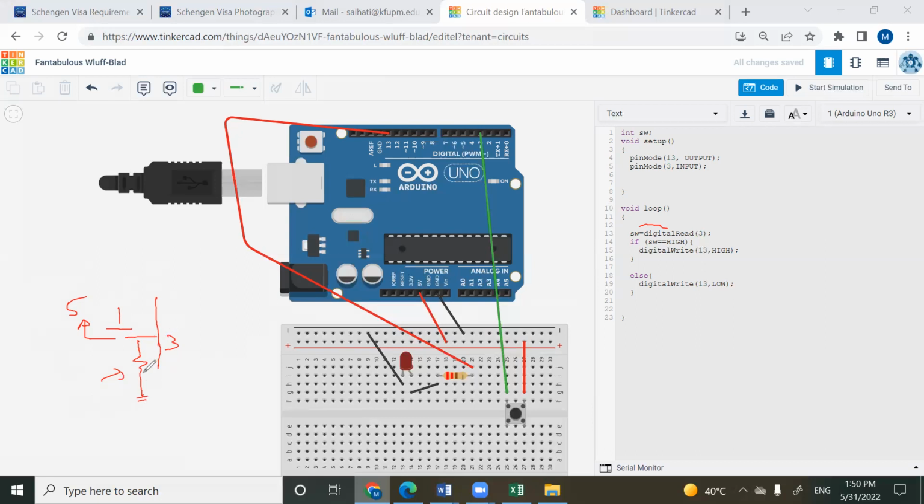So actually this is grounded because there is no current. The input resistance is too high. It is like an open circuit, right? So it's like this. Now, this point is actually the same voltage as this one. There is no current here, so the voltage here is 0, right?